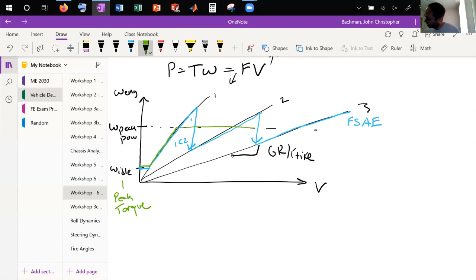And then they're going to come along here until they hit the end of their CVT belt pulling, and then they're going to have to travel along the high ratio of their CVT. So this is the high ratio of their CVT. See, I'm already messing up high and low. And this is the low ratio of the CVT when they hit their low ratio. Of course, those are multiplied by their gearbox ratio too.